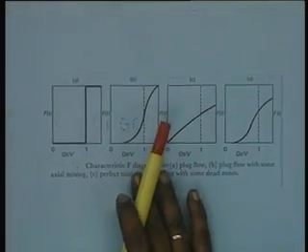Now if you want to quantify the deviation from the ideal state in terms of the F curve, earlier we have seen the use of a C curve for getting the reactor performance. If you want to detect the deviation from ideality using the F curve, consider a CSTR, a continuous stirred tank reactor, given a step change in the concentration of a tracer in the feed stream.